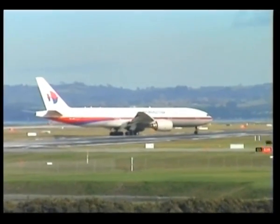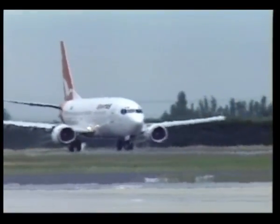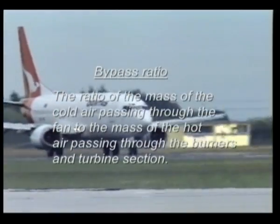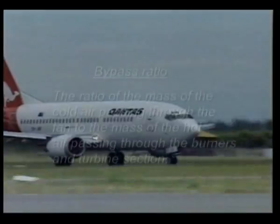Although a turbofan engine is described as though it were a turbojet, its characteristics are determined by the bypass ratio, which, to recap, is the ratio of the mass of the cold air passing through the fan to the mass of the hot air passing through the burners and turbine section.